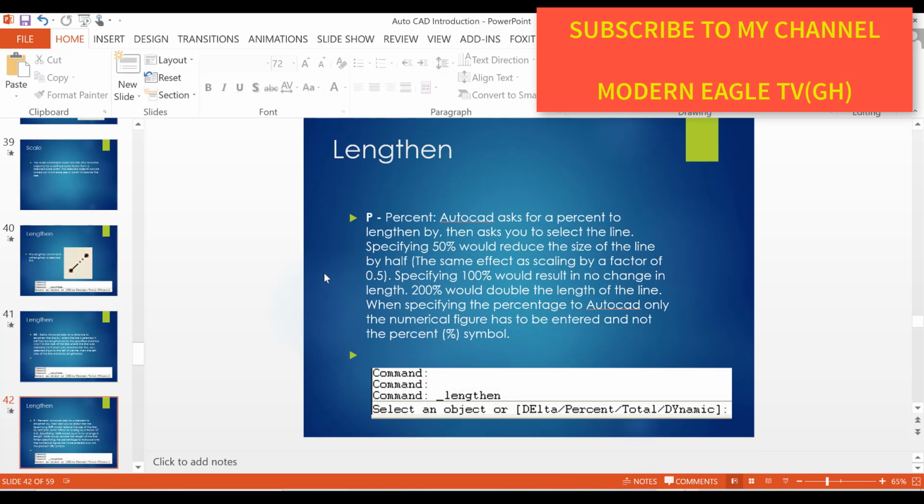Percent, P, percent. AutoCAD asks for a percent to lengthen by, then asks you to select the line. Specifying 50% will reduce the size of the line by half, the same effect as scaling by a factor of 0.5. Specifying 100% will result in no change in length. 200% will double the length of the line. When specifying the percentage to AutoCAD, only the numerical figure has to be entered and not the percent symbol.